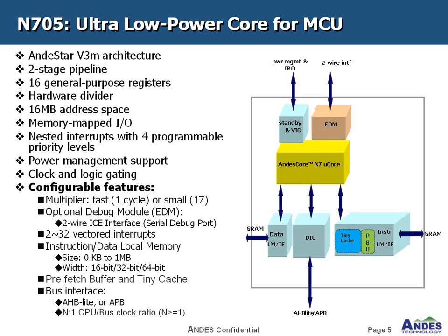The tiny cache is a small cache inside N7. When N7 detects a loop, N7 will cache this loop into the tiny cache. Next, when N7 repeats this loop, N7 will fetch instructions from the high-speed tiny cache, not slow flash memory. It can improve flash access efficiency for loops by about 40%. Both of them can improve performance and reduce power consumption.